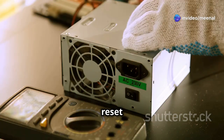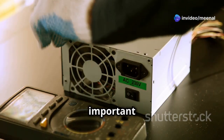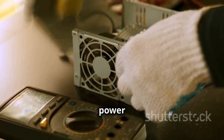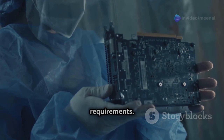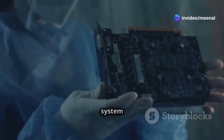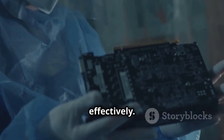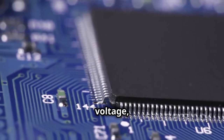Power supply monitor reset ICs generate a reset signal if the voltage drops below a certain threshold. This is particularly important in systems where stable power is crucial, as it prevents malfunction due to power supply issues. Choosing the right IC involves considering your application's requirements. You need to evaluate the specific conditions under which your system operates and select an IC that can handle those conditions effectively. Factors include the type of reset source, reset threshold voltage, and package type.